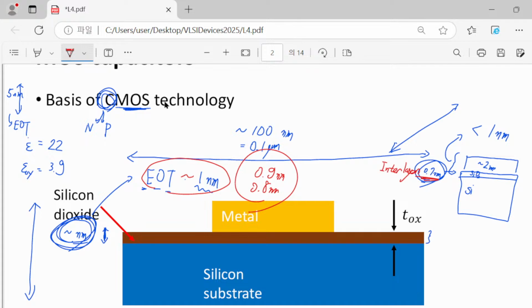But please come back to the other two dimensions, your length direction or length dimension, or your width dimension. In both cases, it is still orders of 100 nanometer. So you may feel that this sounds a little bit difficult, because nowadays we always say that we are now living in the era of 3 nanometer node or 2 nanometer node, but unfortunately there is no real 2 nanometer, real 3 nanometer. So usually what we can get from this structure is orders of just 100 nanometer.